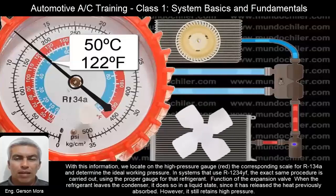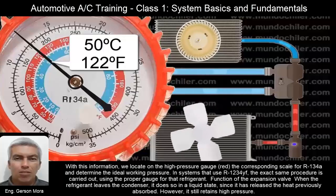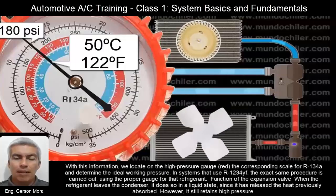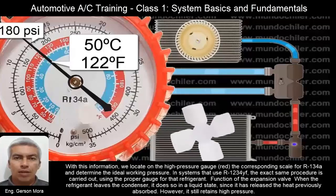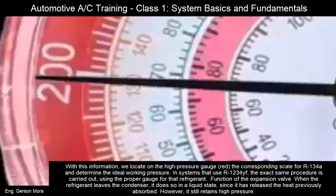With this information, we locate on the high pressure gauge, or red, the corresponding scale for R134a and determine the ideal working pressure. In systems that use R1234yf, the exact same procedure is carried out using the proper gauge for that refrigerant.